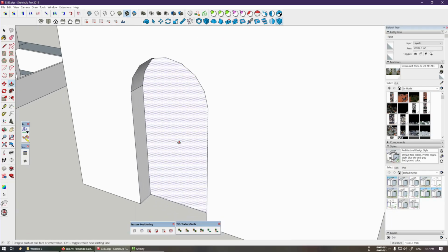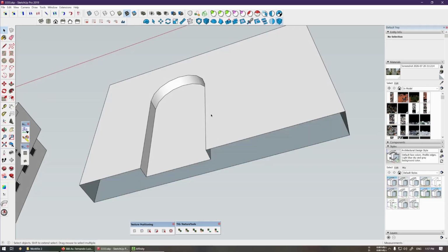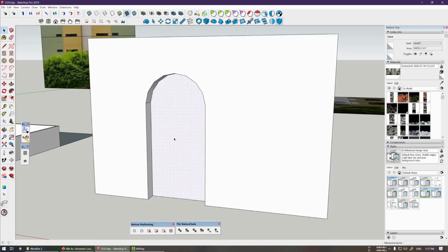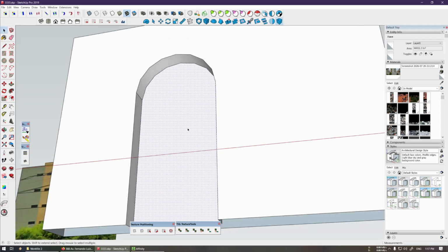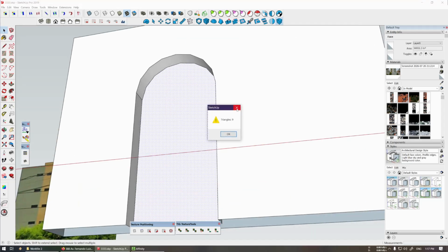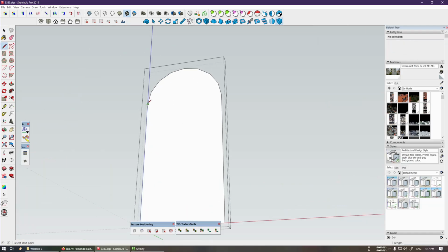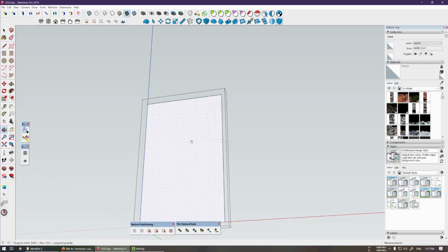And then you extrude it inward. Of course, delete the bottom face, but we are not completely done yet. Notice this door, the one that we inserted, is 9 triangles. We can reduce this. Group this. Delete the top. Now this is just 2 triangles.